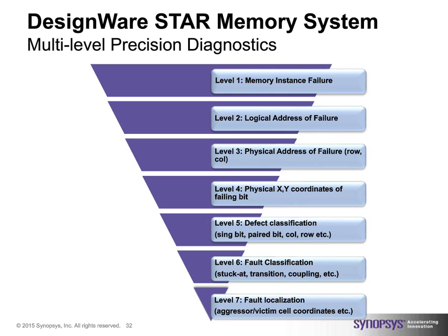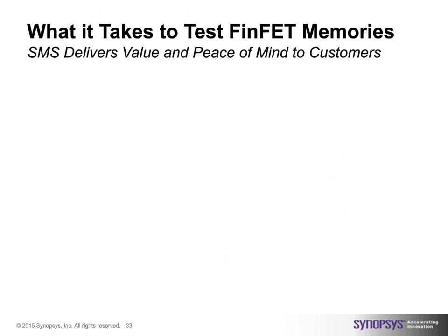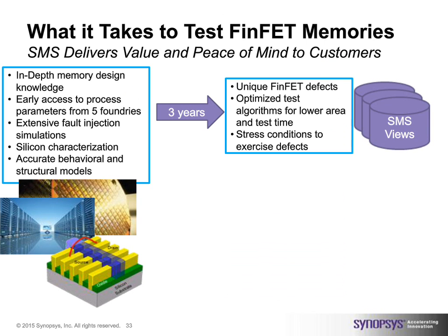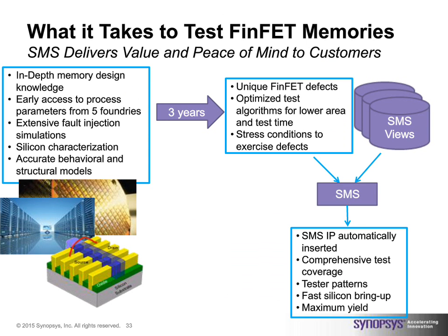So in short, what we're trying to do here is we're trying to look at the memory design itself, the cell designs that is, do the injections, do the extractions, look at the models, and accordingly create the test sequences and the algorithms. A user needs to have the algorithms and use them, but use them under the different stress conditions necessary, that is the different corners necessary. The SMS engine itself, while we upgrade it to be able to handle the different test and diagnosis features, at the same time, we also make it programmable for it to be uploaded as necessary.